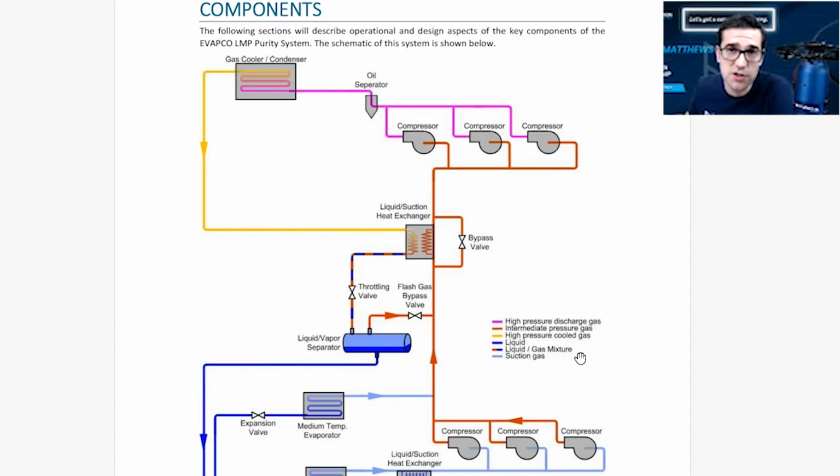This is some of the differences that maybe someone didn't teach you. You're going out to do a construction job on a new CO2 store. You never did one before. There's different rated pipe, whereas before you had all the same pipe in that tractor trailer that comes in with all your tools and your fittings. It would be all K, we'll say, for a regular HFC store. Now today it may not be. Different sections, you can see, look, different sections of this could be different pipe types.